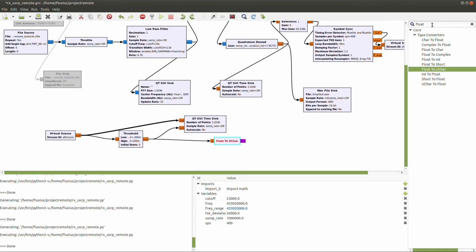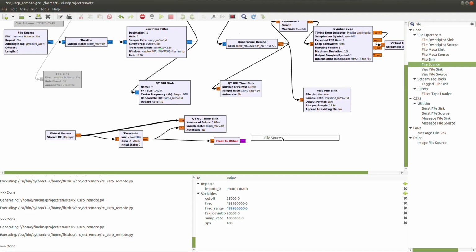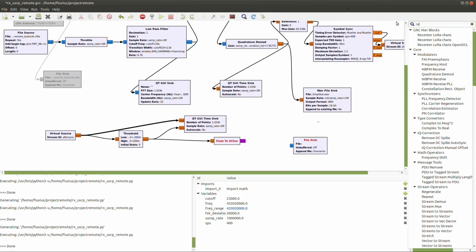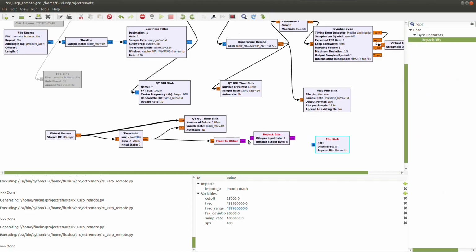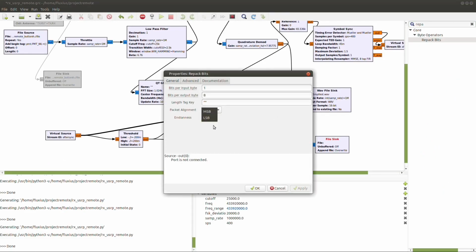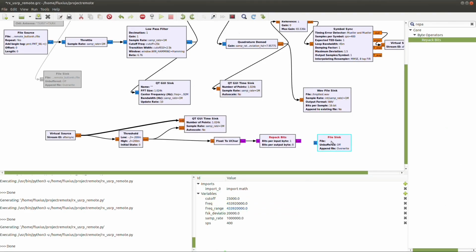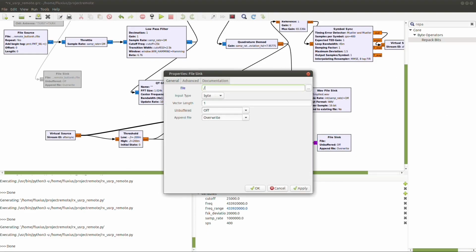And then I will also produce a file. But if we just put everything in the file sink like that, we'll just have some bytes that represent 0, 1, 1, etc. So we have to repack the bits. We repack bits, we use MSB. So we just get one bit and assemble all the bits to form 8 bits in order to output 1 byte out of that. So it's just repacking stuff, right? So then we can output everything in the same format.